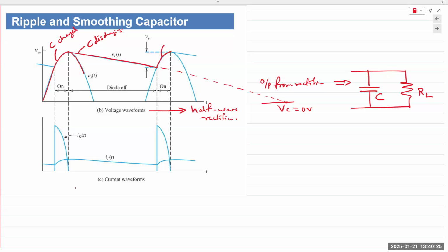But before it can discharge even 10% of its energy, the next charging cycle arrives and the capacitor begins charging again. And then the cycle continues. In the positive half cycle, when the diode is on, the capacitor receives the energy, charges up, and reaches full load. The diode turns off, the capacitor is not receiving any more charge, and it is now releasing the energy back into the circuit. Since the diode is reverse biased, all of that energy is going to go to the load resistor.